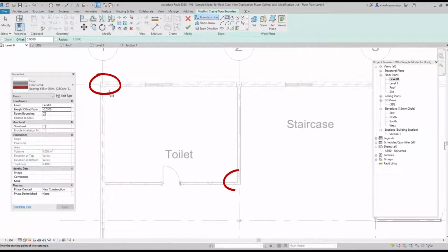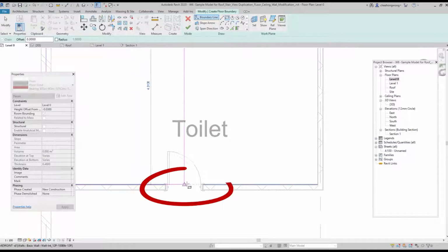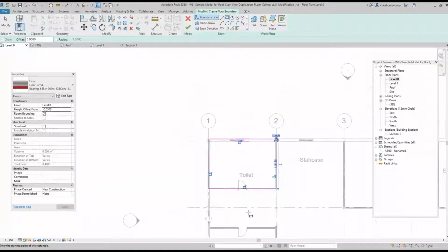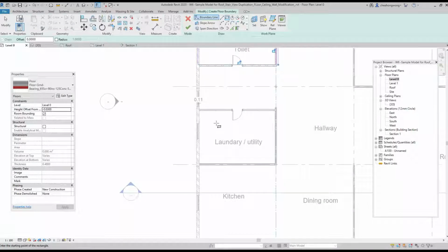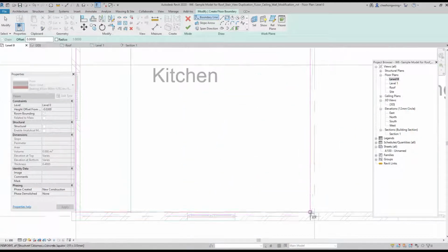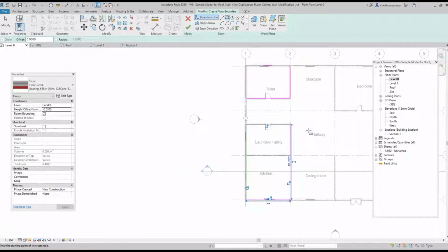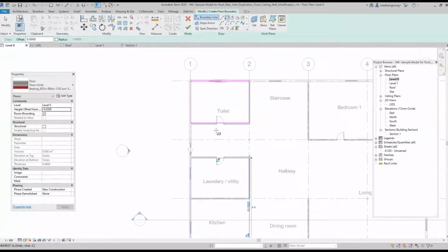Always start from the center line of the external wall and stop at the center line of the opposite wall of the starting point. Make sure the edge of the slab at the door side aligns to the inner face of the toilet wall. This makes sense because when you walk into the toilet, the slab will drop from inside of the toilet. Now in the Properties palette, set height offset from level to 0 and place the slab between toilet and utility.